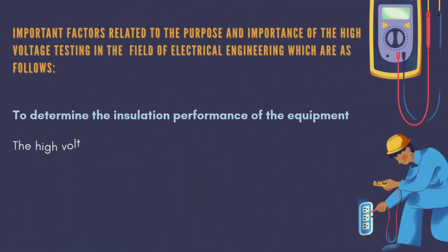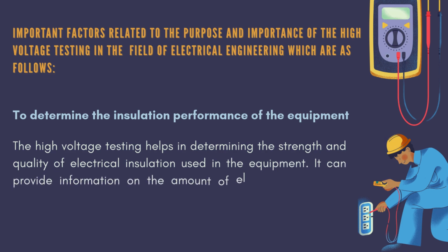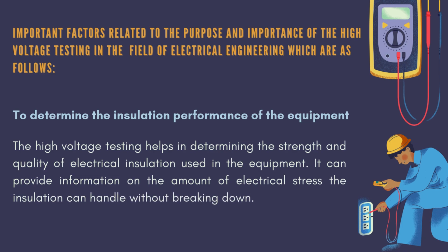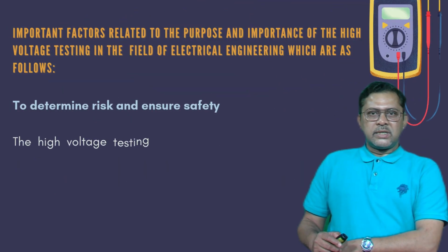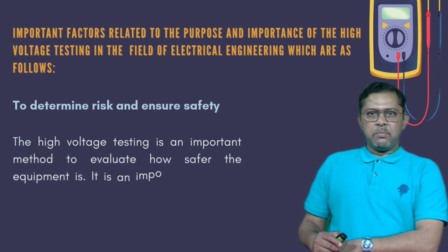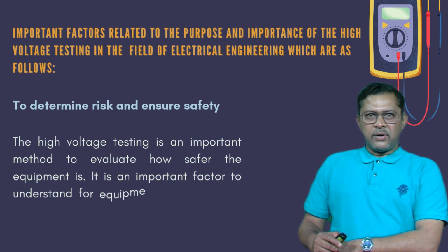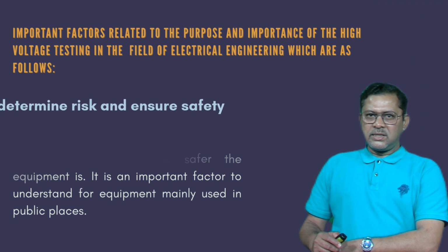First, to determine the insulation performance of the equipment. The high voltage testing helps in determining the strength and quality of electrical insulation used in the equipment. It can provide information on the amount of electrical stress the insulation can handle without breaking down. Second, to determine risk and ensure safety. Here, the high voltage testing is an important method to evaluate how safe the equipment is. It is an important factor to understand for equipment mainly used in public places.